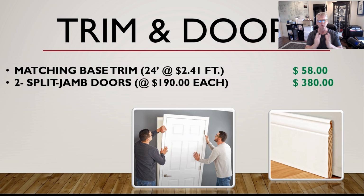Split jam doors are doors that come apart at the center of the jam. There's 2 halves. The casing's already on there. The trim's already applied to both halves. You set one side. You bring the other side of the split jam in. You squeeze them together in the door opening. They make one door. Real simple, real easy.